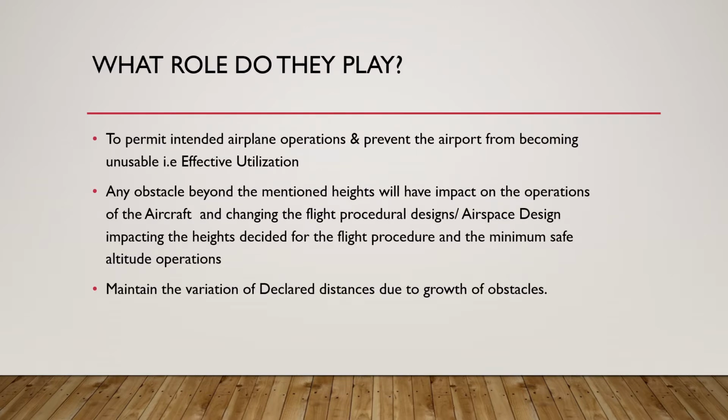So what role does the obstacle limitation surface play? We all know the development cost of the infrastructure for a bigger airport involves huge financial investments. So in order to effectively utilize the designed aerodrome, it is important to develop the obstacle limitation surfaces. If there are infringements to these surfaces, this will have an impact on the operations of the aircraft. That is, in case larger aircraft tend to operate from that particular aerodrome, an increase in the height of the obstacles will lead to